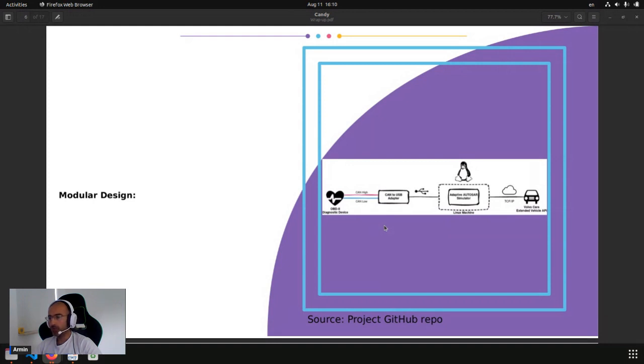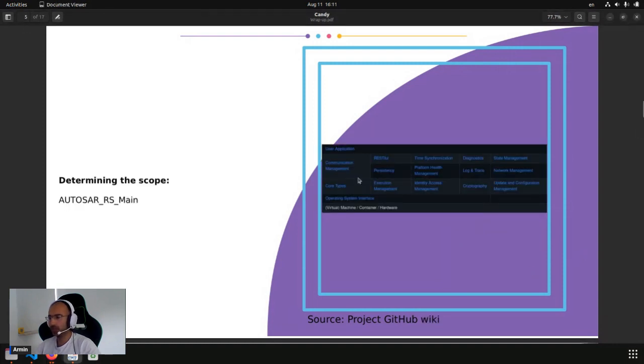So you have this OBD emulator project, which I also started in parallel with the AUTOSAR, that can handle your communication within the CAN network outside of the AUTOSAR project. So you're also not really required to have a specific type of hardware for the simulation, because if you take out that component, you can replace it with your own hardware driver for the CAN communication, and you can basically do the same thing. So this part also became outside of the AUTOSAR project, and I came up with the last part, which is the application layer, which I explained here.